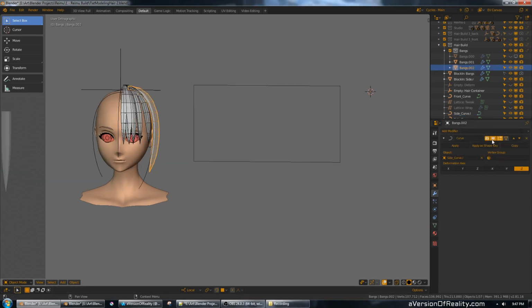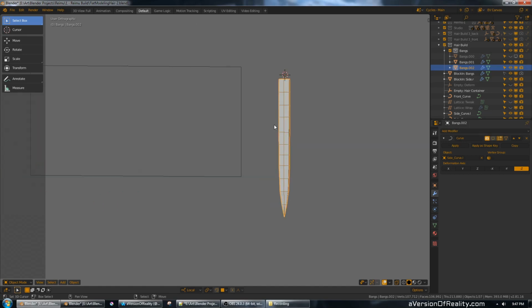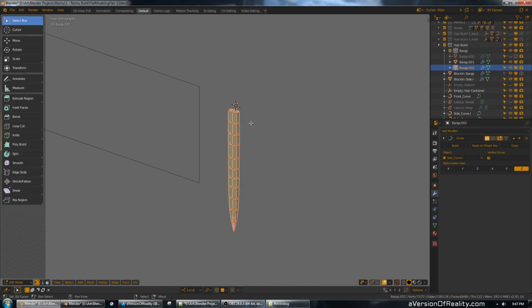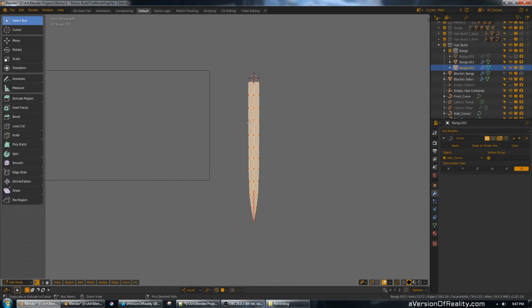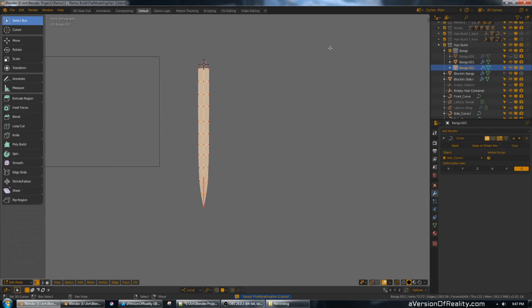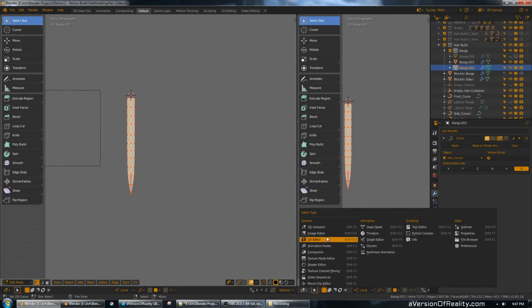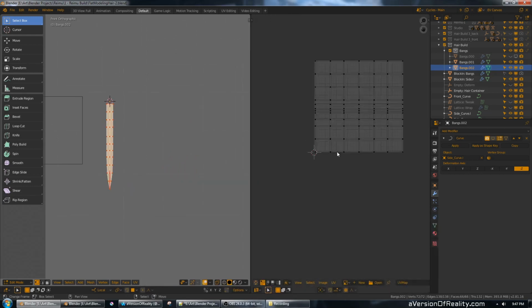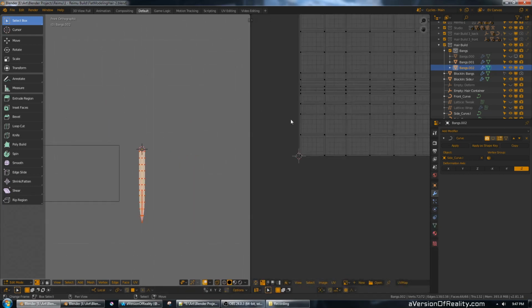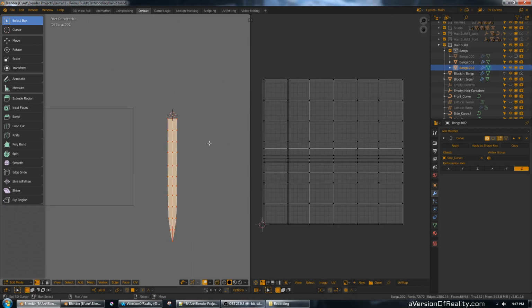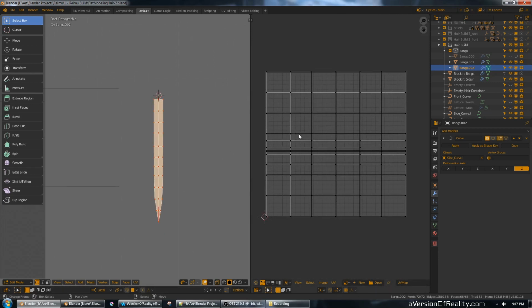Now that we've got our shape blocked in, we can start duplicating our spike, merging and bridging things, and build up a better shape. Before that, we have a little bit of housekeeping, and that's the UVs, which we've been working to preserve. But I went ahead and added a bunch of loop cuts with no regard to the UVs. And as you can see on the UV map, the cuts are not evenly spaced. That's because the UV is updated when the cut is made, and it does not update when I move things around.